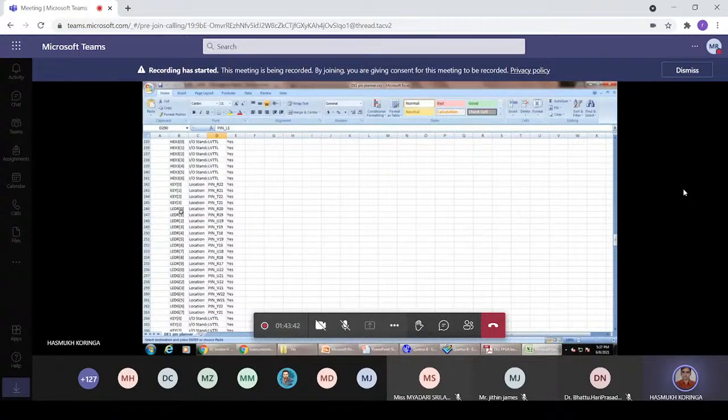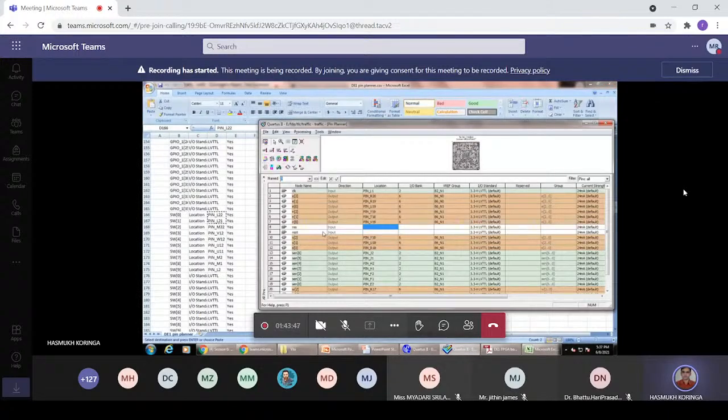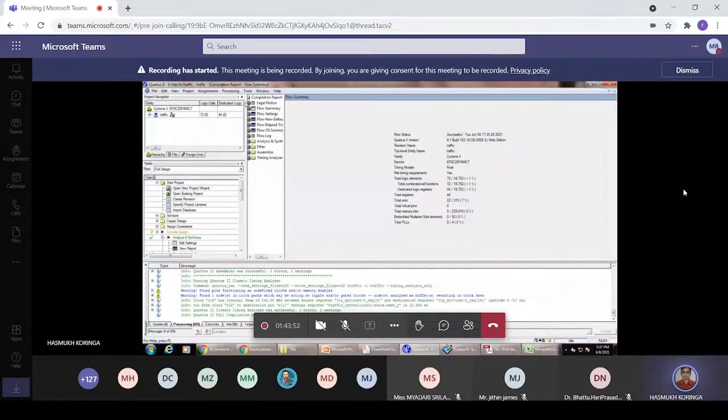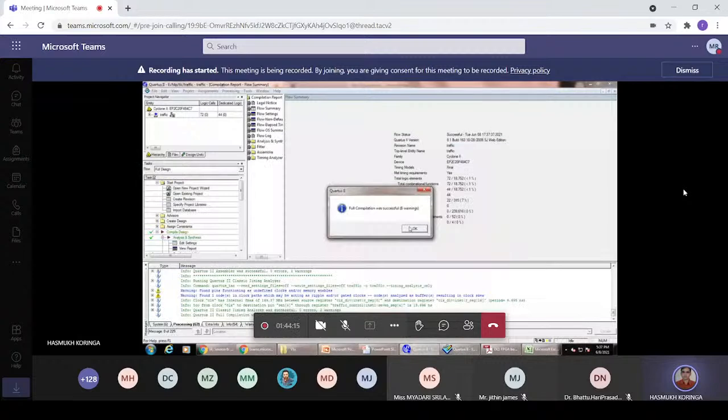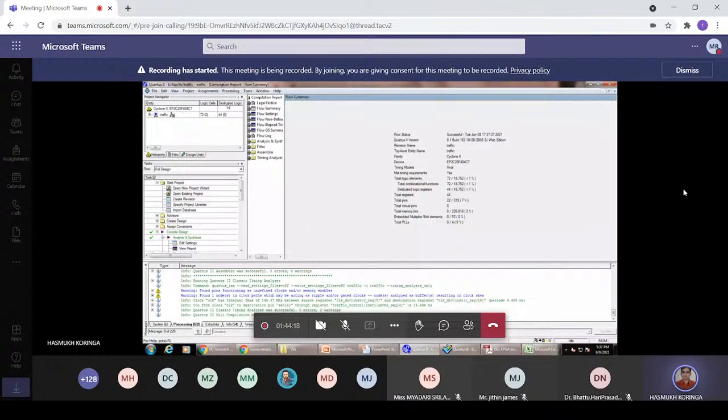And to switch for the reset for the clock divider and for the traffic light controller. So once we assign the pins, we need to recompile the design. Once it's compiled, then download it on an FPGA board.